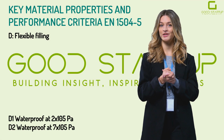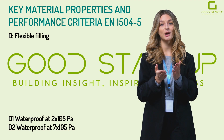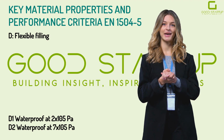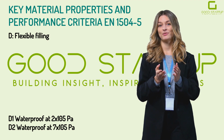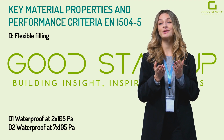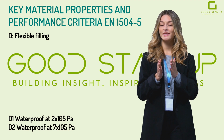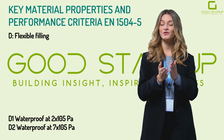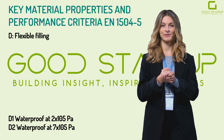Flexibility and water tightness. For flexible sealing materials, performance is measured by their ability to remain watertight under pressure and accommodate movement. EN 1504 Part 5 defines classes like D1 and D2 based on a water pressure test. For example, D1 must resist water ingress at up to 2 times 10 to the power of 5 Pa pressure. These materials are not primarily load-bearing, so instead of bond strength, their key criterion is that they do not crack or leak when the crack opens slightly or when water tries to push through. They are typically tested for elasticity and sealing up to a certain crack width and pressure.